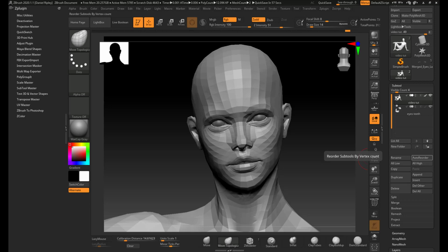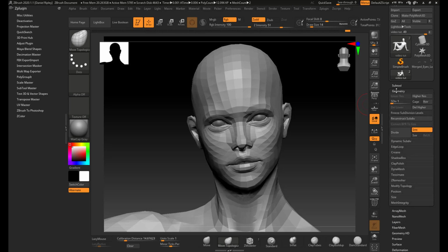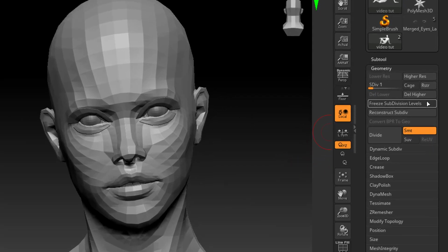So you've done all your sculpting, and now you're preparing to do the displacement. Now if, like in this particular case, you end up deforming the mesh way more than just sculpting detail, then you may want to update the model inside your external application to be your new base mesh. The way that I like to do this is to push into a new layer inside ZBrush, and then with that new layer I use this feature found in the geometry, and it's called cage.